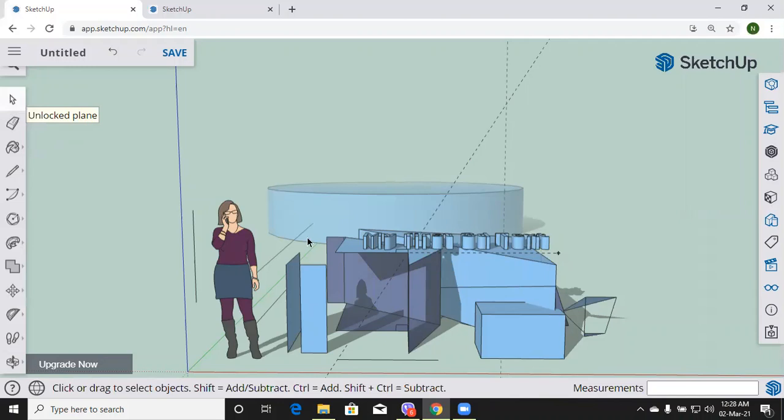So select the tool, select the object. Whichever object you want, you can select. Use the select tool to select the object to be edited by clicking on it, and by default SketchUp selects the subcomponents of objects such as single sides or faces.